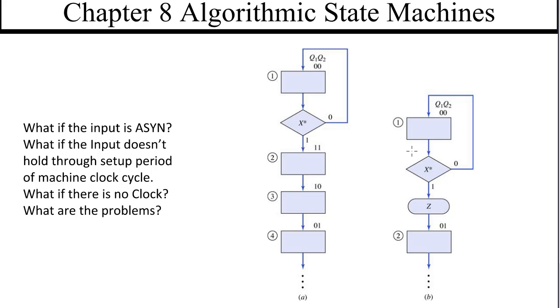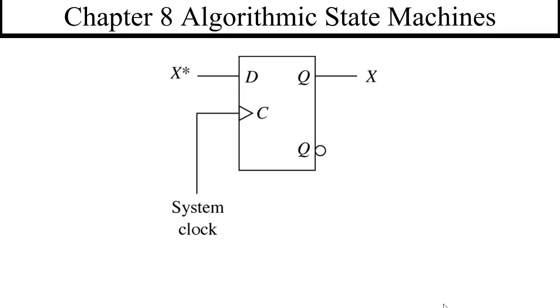The good news is that there are logical ways to think about and solve these issues. What ultimately limits the speed of an algorithmic state machine is the speed of light. But before we talk about the speed of light, just the fact that one wire is longer than another wire causes a timing glitch. Those get exposed as you clock the machine faster and faster.